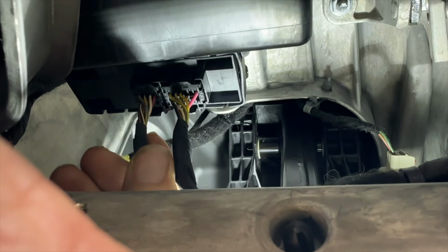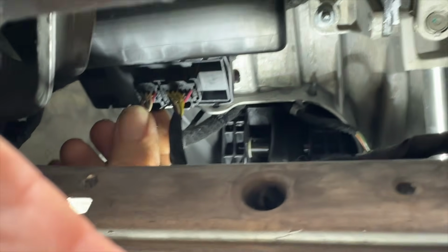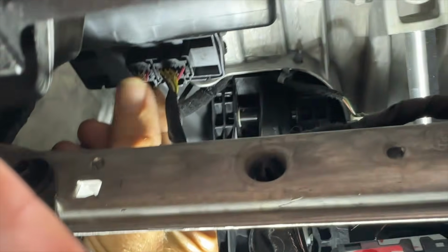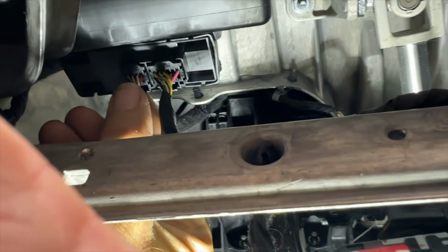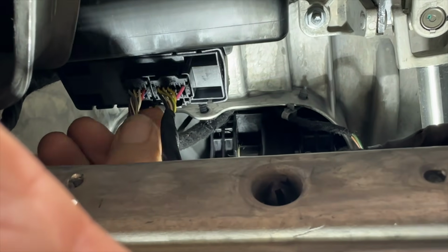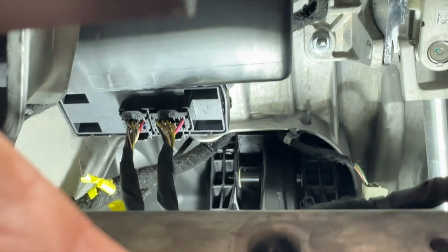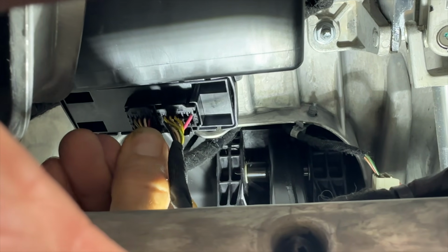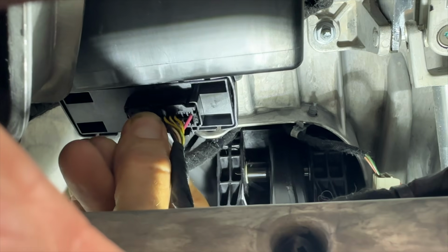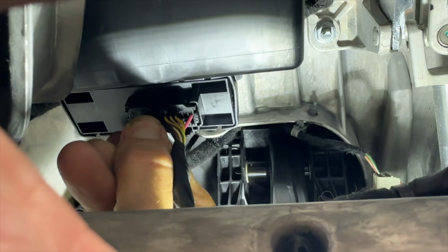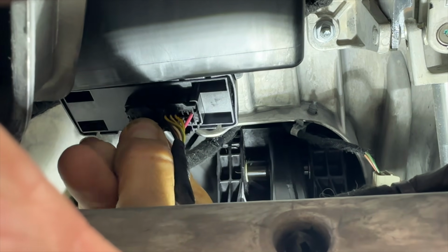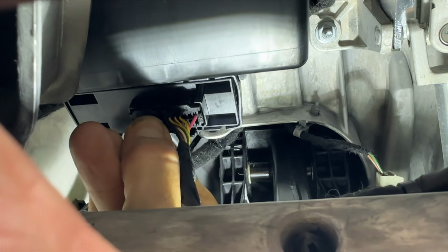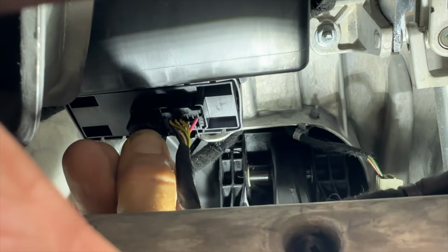Okay, I'm gonna get here in my iPhone, and it's really hard to get a good image of this, but basically you wanna go to the back side of the connector and push down on a clip. What I'm gonna do is push on it and then just kind of swivel it back and forth just a little bit as I'm pulling. And then that's gonna hopefully let me get it out of there. And got it.